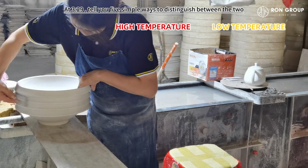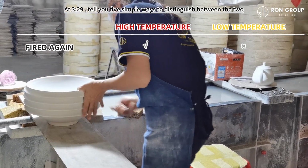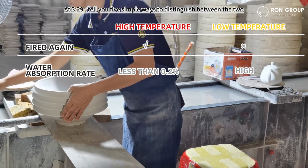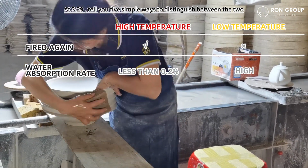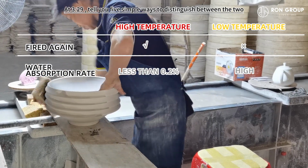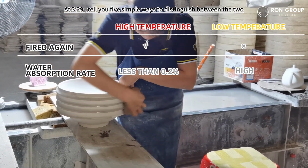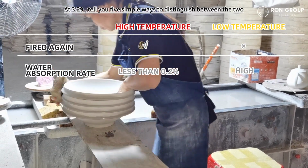There are 5 main differences between high temperature porcelain and low fire porcelain. First, high temperature porcelain can be fired at high temperatures, and low temperature porcelain cannot. What's more, the water absorption rate of high temperature porcelain is lower, less than 0.2%, and it is not easy to absorb stains. And low temperature porcelain has high water absorption and is not easy to clean.